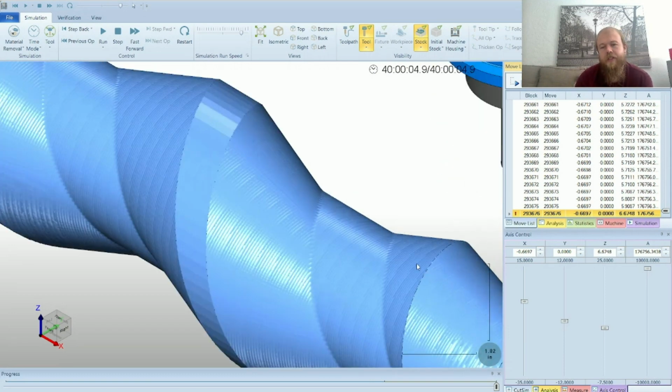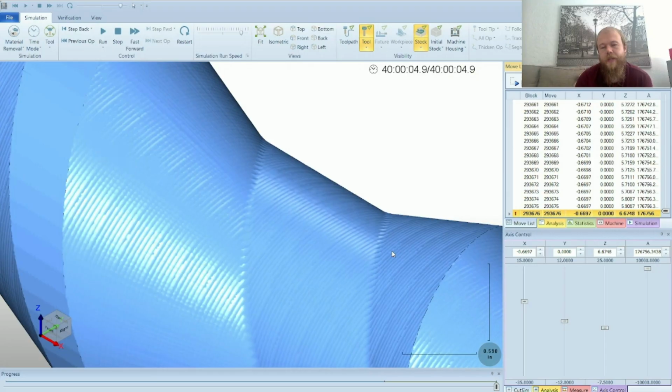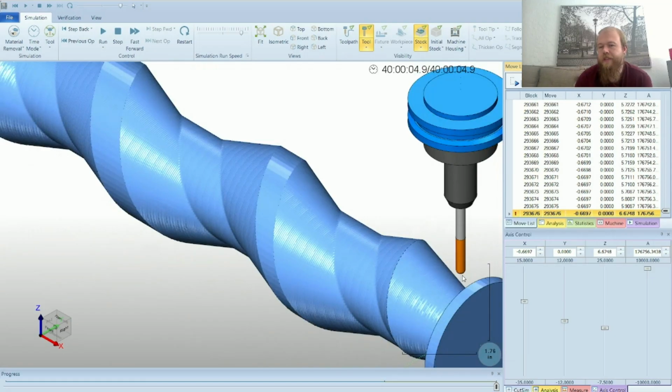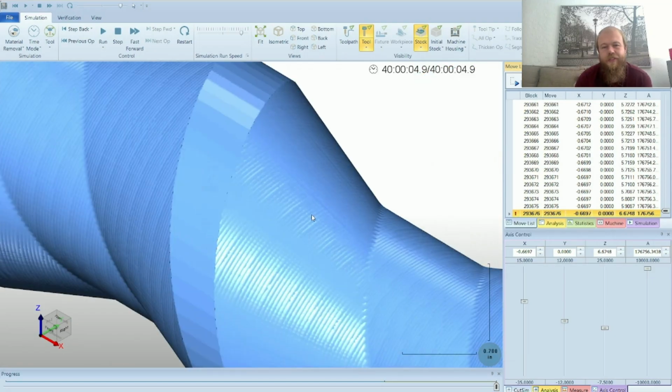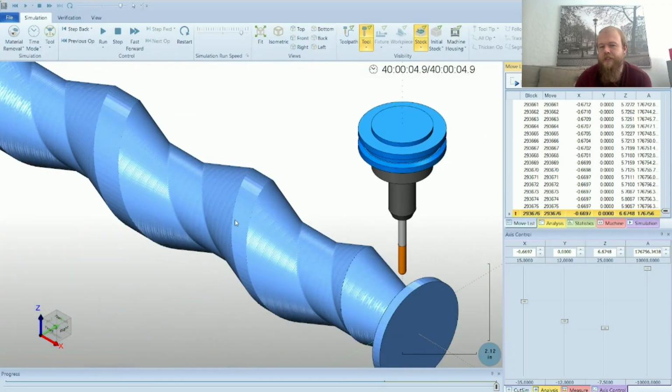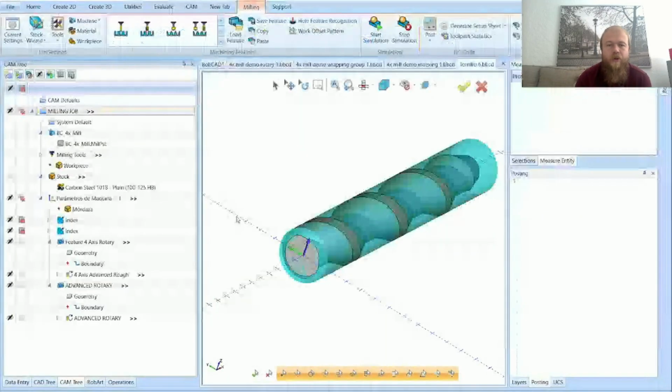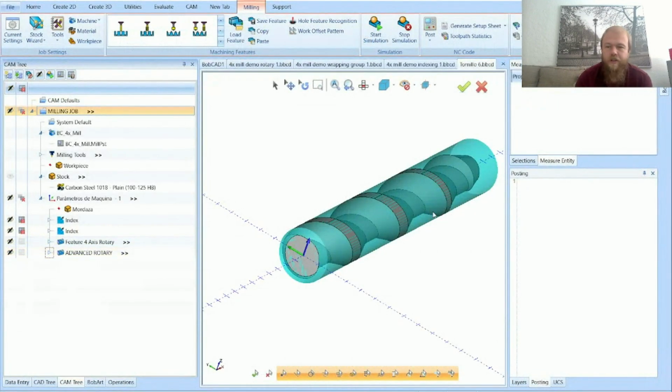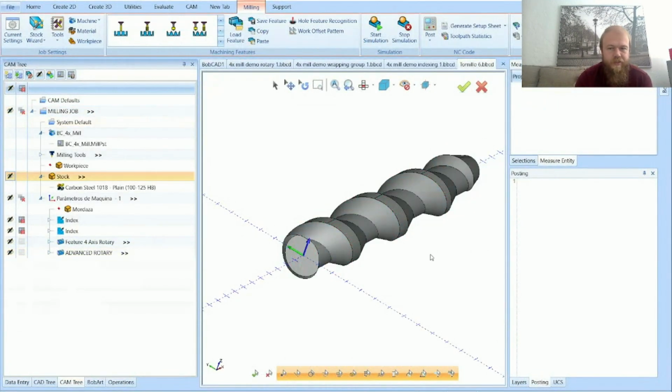So I think this is probably a good one to cover here as well, because we have the advanced finish, which is sort of, you can see the tool marks here, it's sort of following along in a cylindrical shape. It doesn't follow along the pattern necessarily from here to here. So if we want to focus on a specific surface here, what I could do is one of our 4-Axis Pro operations. I've deleted them, so I'm going to just start from scratch.